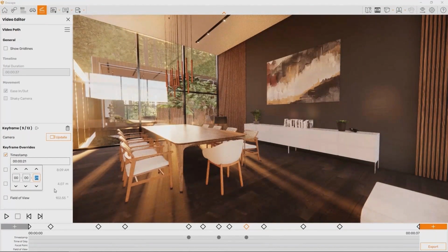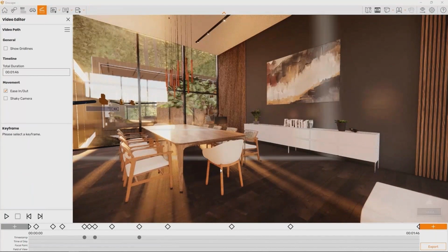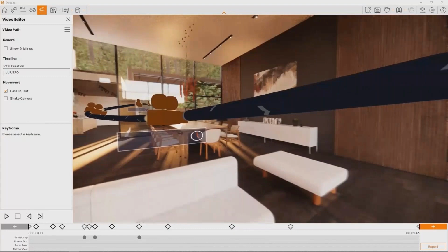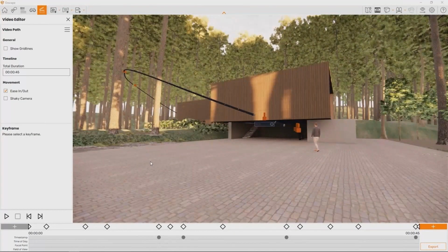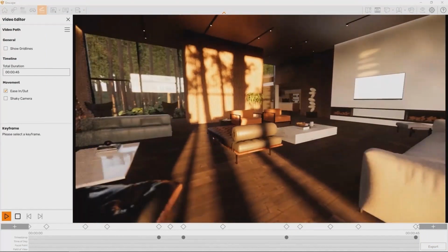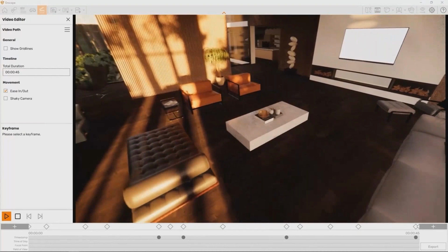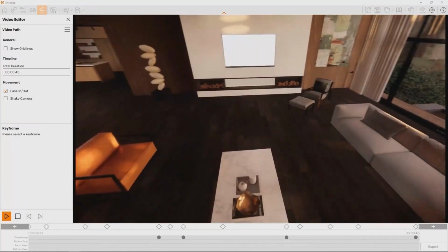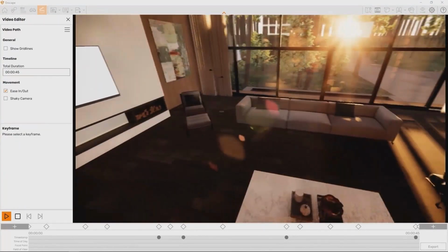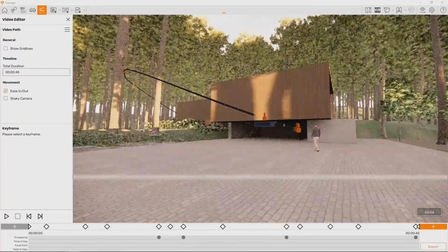Now I'm dialing it further up, so I'm slowing down the area we are, or the way through our living room here. And lastly, I'm also going to dial down the number in my last keyframe here, or my second to last, and pressing P or this play button in the lower left corner to preview my path and get a feel for the speed and for the aesthetics of the whole video fly through. So yeah, I think that's all right.